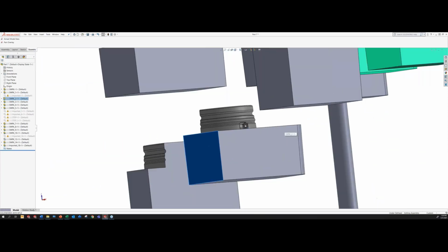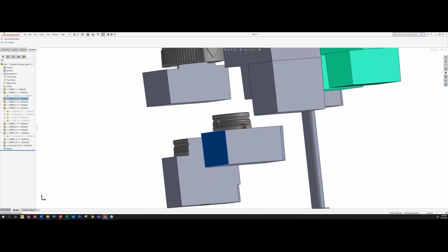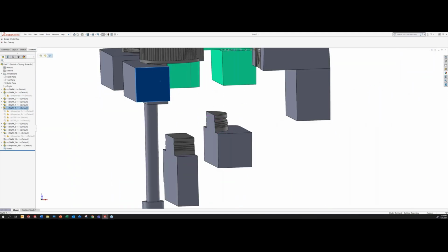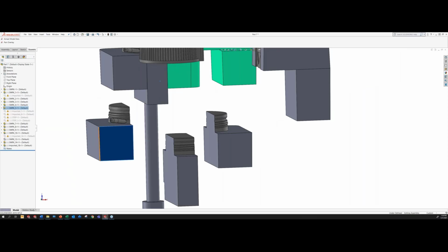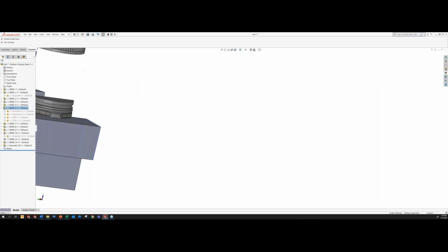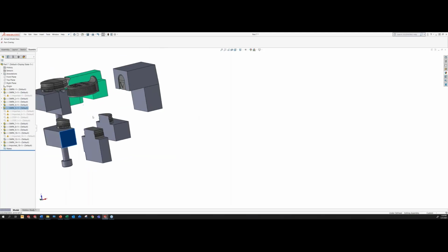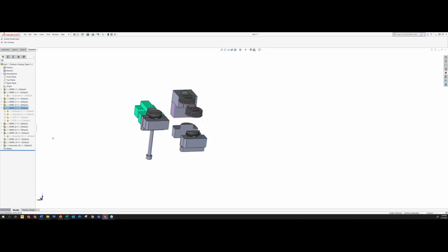In a production setting, you'd have a lifter of some sort. And then the same goes for the other side. It pushes in, falls out, and creates the other two lock features. And then put all three pieces of metal back together, put them back in the tool, and repeat.